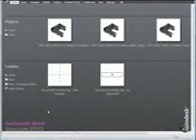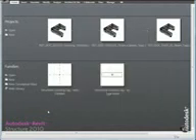In this lesson, you will learn how to use shared parameters to define additional elements that are usually not included in the beam schedule when it is created within the project template. You can add shared parameters to any family regardless of category. They are defined and stored in an external file, ensuring consistency across families and projects. Their values may also be aggregated and reported within Revit Structure multi-category schedules.